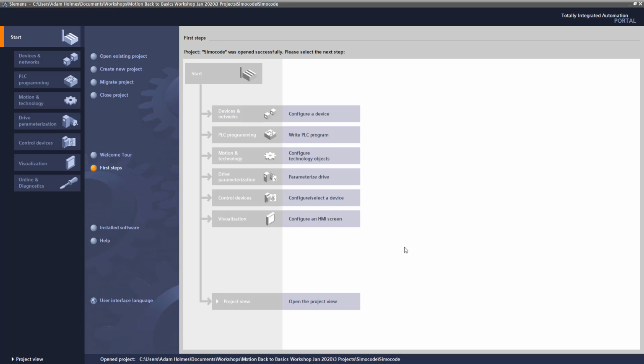This is a really quick video just to show how we can connect our SIMOCODE Pro V PROFINET device to an S7 PLC, whether it's a 1200 or 1500, it doesn't matter. I'm using an S7 1500 for today's demonstration, and I'm going to show you how we can connect the two devices together via the PROFINET network, and we will be able to control our SIMOCODE from our PLC